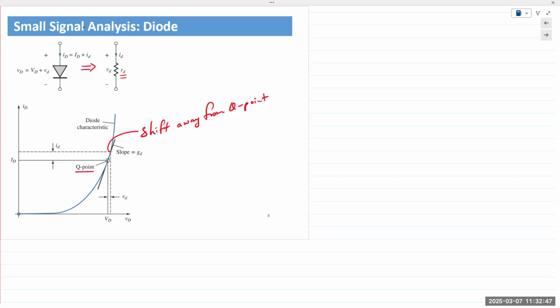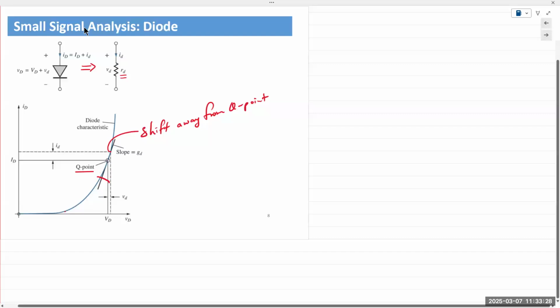So all the points that we're talking about, they're all lying on the diode characteristic. Remember, I said you can find the DC or static resistance by choosing any number of points on the diode characteristic. If you choose any point, let's say above this portion, more likely than not, the diode resistance would be very, very similar. But if you choose something here, then the diode resistance might be different.